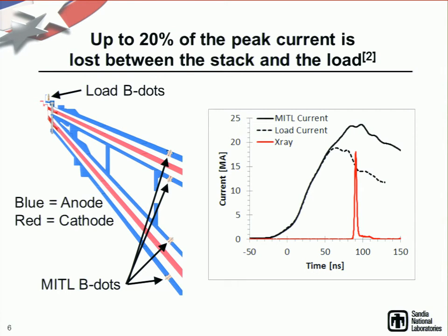And as I mentioned, you have this compression of energy flowing through the machine, such that at this point you have such high energy densities that you start to get plasma formation, which basically kicks off hydrocarbons that are absorbed into the material. And that causes a gap closure, which can short out your pulse and drop the current by significant amounts.